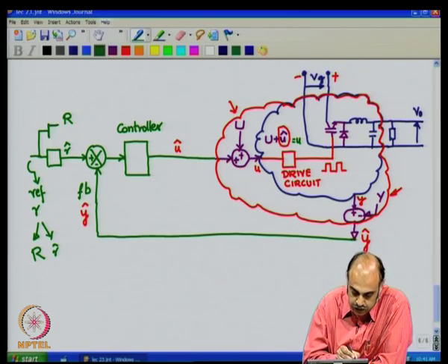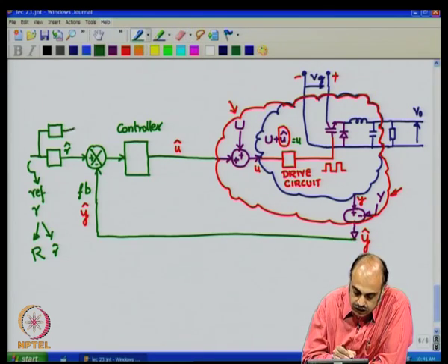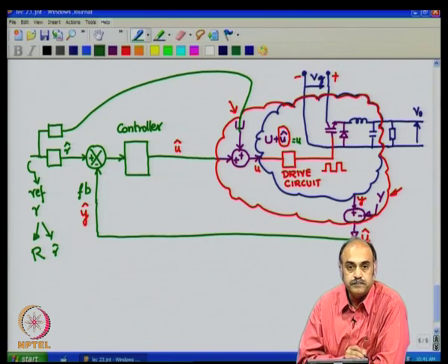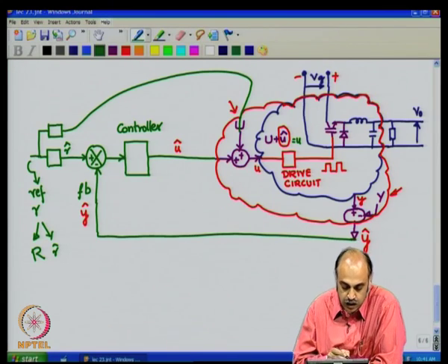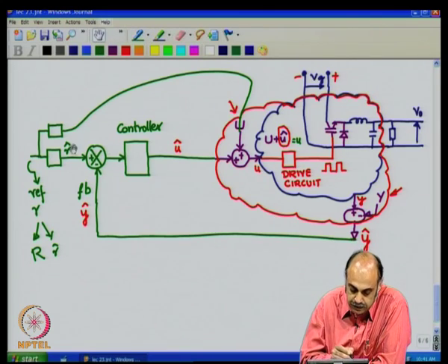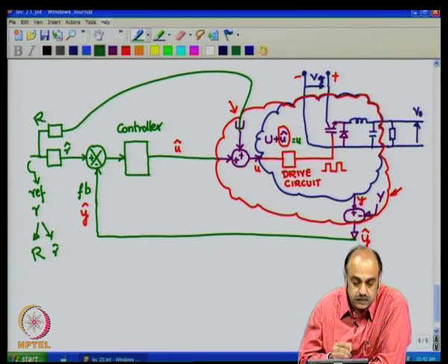and there should be something here which directly takes the R part here and gives it here. So, the steady state part is directly given, the controller is bypassed. Observe that the controller is bypassed for giving the steady state part of the reference. So, this would be the R part of the reference.